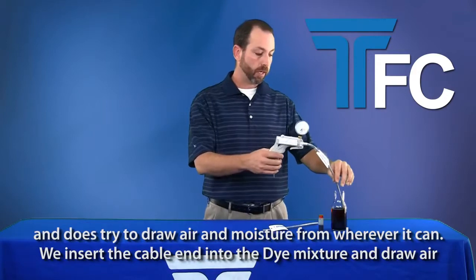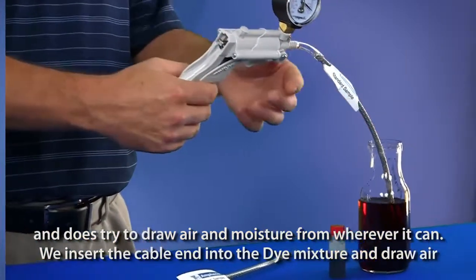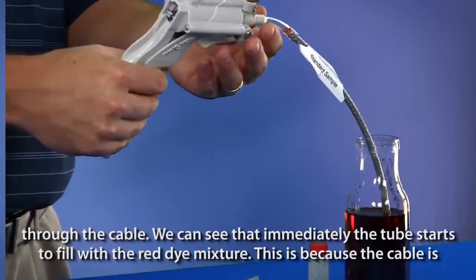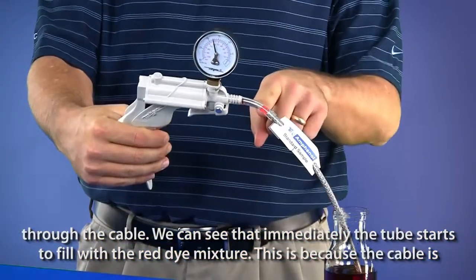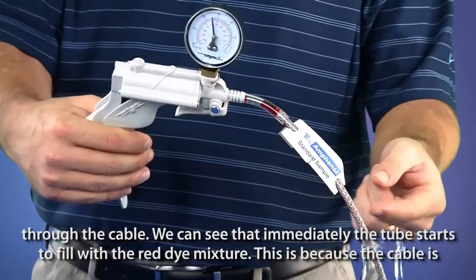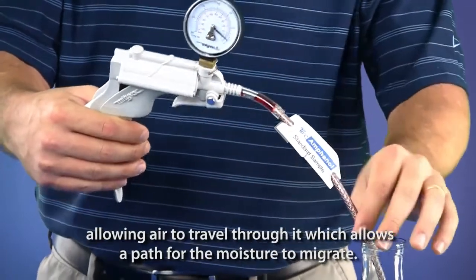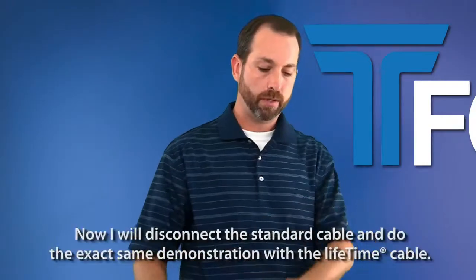Now we insert the cable end into the dye mixture, and I'm going to draw air through the cable, and we can see that immediately the tube starts to fill with the red dye mixture. That's because the cable is allowing air to travel through it, which allows a path for the moisture to migrate. Now I will disconnect